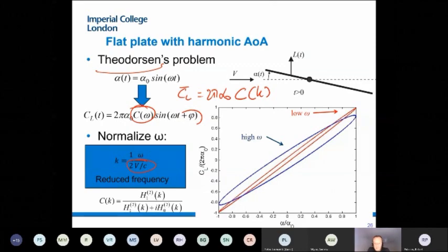Physically, what it means when you have a system that has phase delays and amplitude delays is this: if you were to plot lift versus angle of attack on an airfoil, as I defined at the beginning, for a steady airfoil you have a straight line when you normalize things by 2 pi. There's a constant that appears in airfoil theory. That straight line will start to have the shape of an ellipse when you start looking into phase delays.